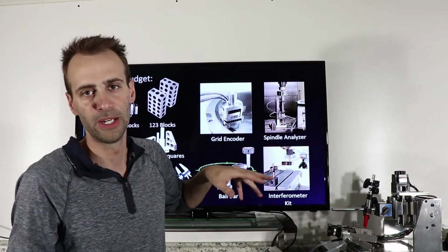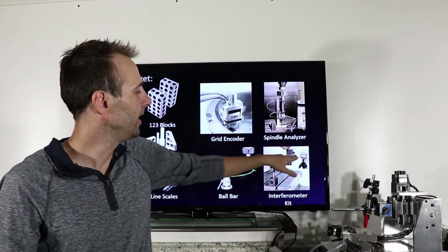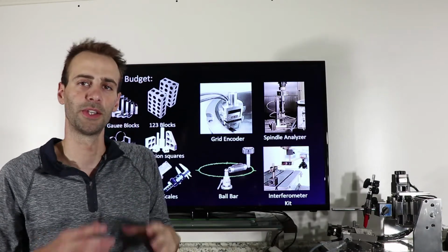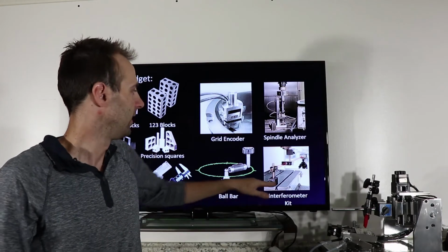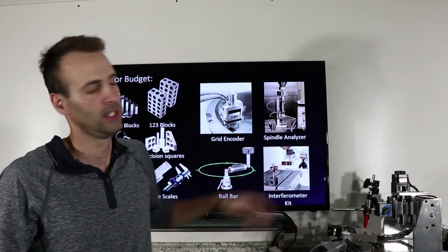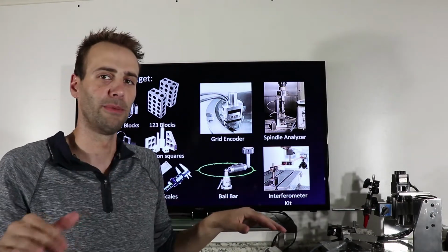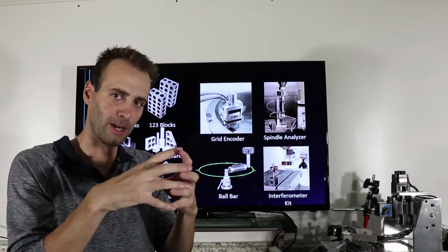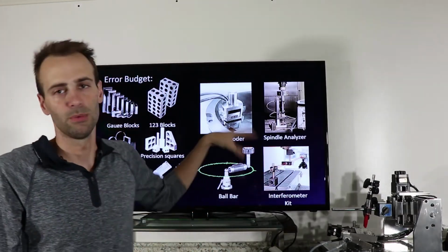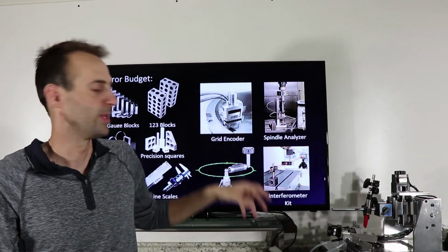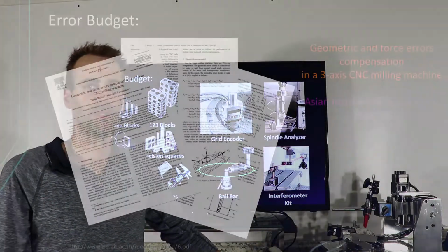So it just might be a good time to point out that anytime you're measuring your errors, you want to do it where you normally manufacture parts, okay? So that's why they're doing this sort of up off the table, right? They're not measuring on the table, they're measuring where the part would be and then shooting the laser through that. We may go into some more of this in another video because these are already so long.